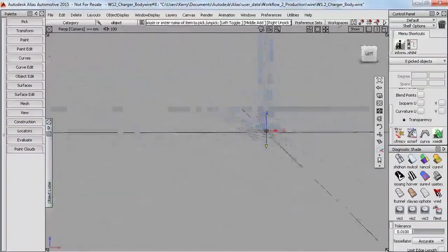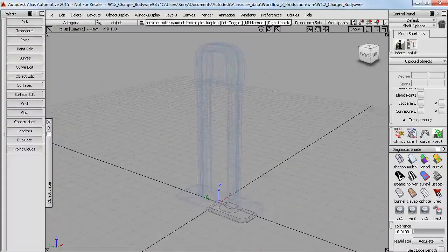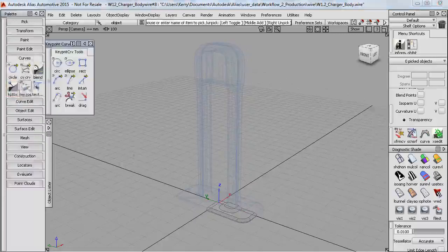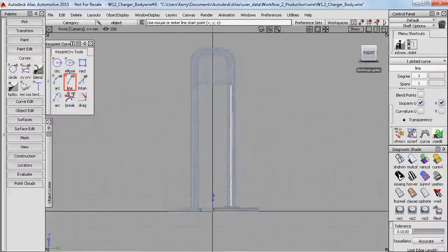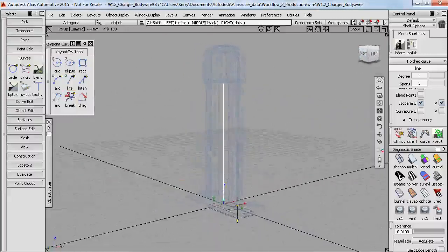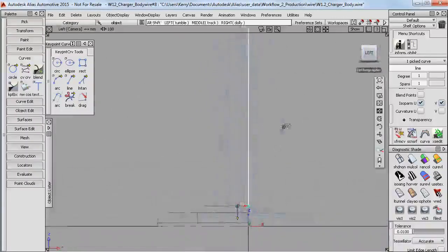And for the front surfaces, all I'm going to do is create a slab that follows this profile. And I'll use key point curves and start by snapping onto the top of the raised up part of the base. And then just do a vertical line, and I'll just guess the height for now. And then I'm going to move it horizontally to the centre line because I just want to build a quarter again. And then in this view I'll give it some depth.